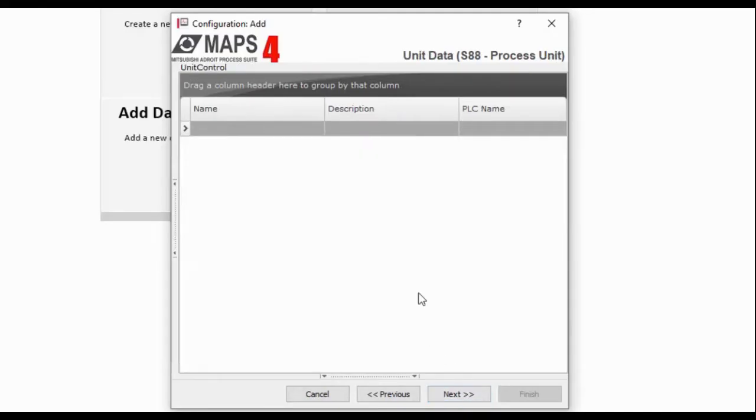In this next step we have to set up the process unit. A process unit is a process within the plant area. This unit consists of all the equipment applicable to that process. You can have multiple processes in the plant. For example, the northern suburb can have 2 pump stations. Each pump station has their own electrical and instrumentation equipment. For this project we'll only have 1 unit. This unit will be called Section 01, and the description will be called Demo Section 01. We'll then assign this unit to the Demo PLC.